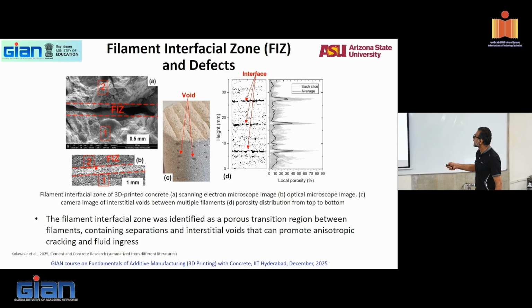You're normally looking at around 5% porosity in the bulk of your concrete. You see that? And when it comes to the interface, what happens? You look at 30-40% porosity. You have 8 times the porosity in the interface than in the bulk. What is the ramification? Whatever I do to make my bulk great is useless now in terms of properties.